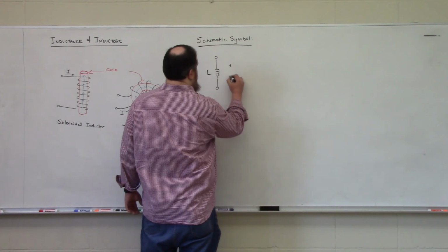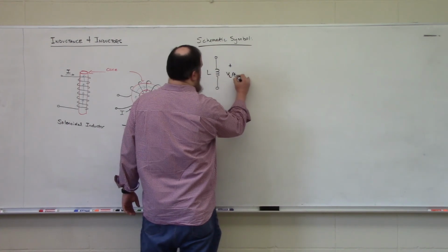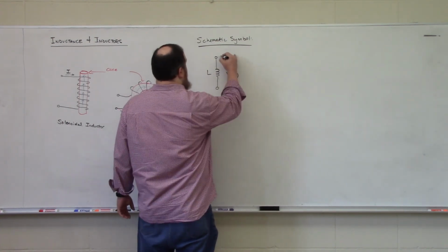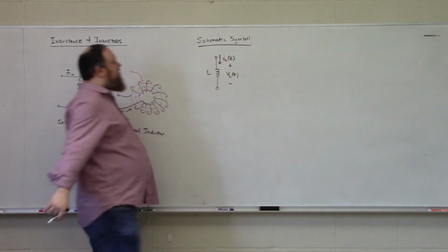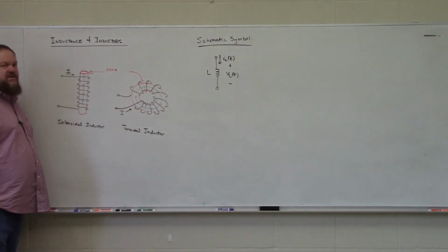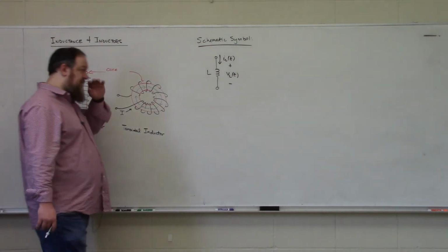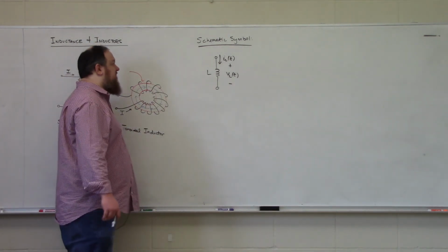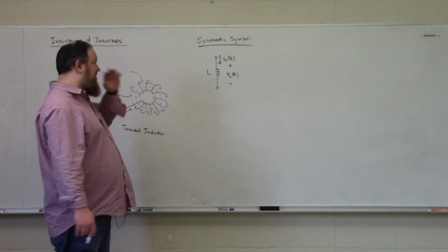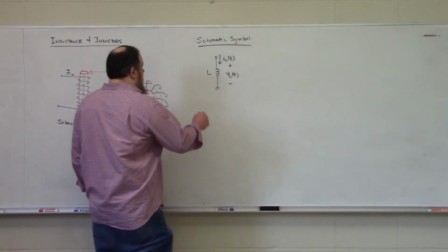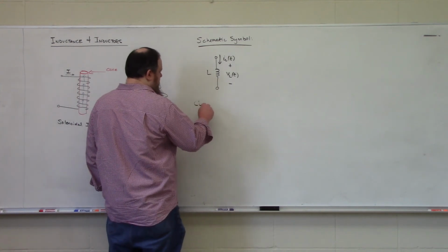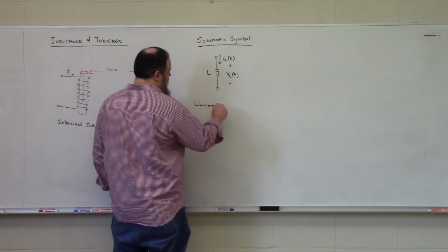If there is a voltage drop, VL over the inductor, then this guy will be absorbing power when a current IL flows into the positive terminal. So inductors also obey the passive sign convention because they are passive elements. They exhibit inductance whether or not voltage or current flows through them. All right, current voltage relationships.